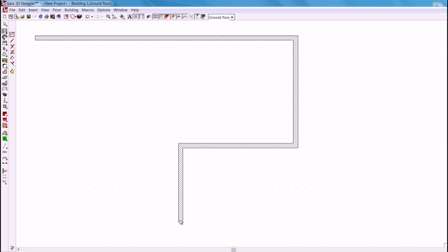move the mouse, and click again. I will now right-click to stop drawing the walls for a moment and put a guideline in to make it easy for me to meet up with where I started. Click on this button, which will bring up more options in a column to the right-hand side. Make sure Vertical Guideline is selected. Move your mouse so the guideline is next to the wall we want to join to and click to confirm.